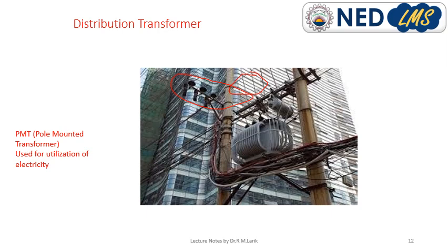Remember that transformer efficiency, it is not an ideal transformer but a practical one, so its efficiency remains 96-97%. Why? Because in a transformer, the energy form is not changed. Electrical energy cannot be converted to mechanical by a transformer, or mechanical energy to electrical. That job is done by generators. Transformers just change the voltage levels, without a change of frequency. So its efficiency is almost above 95% because the energy form is not changed in transformers.